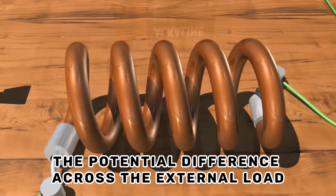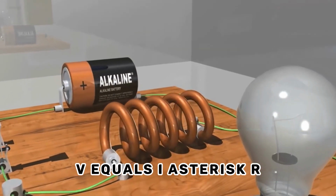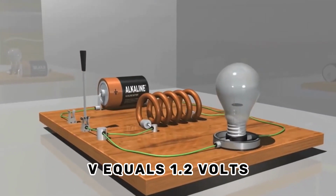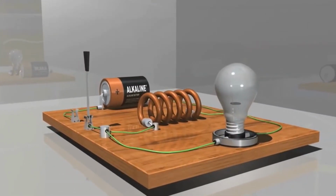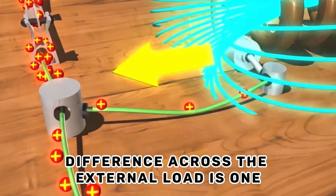The potential difference across the external load can be found using Ohm's law. V equals I * R. V equals 0.6 amperes * 2 ohms. V equals 1.2 volts. Therefore, the potential difference across the external load is 1.2